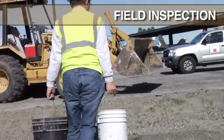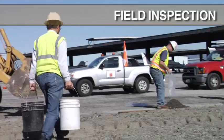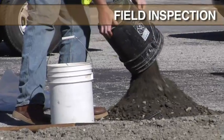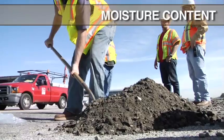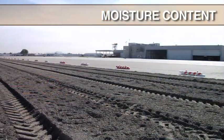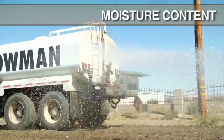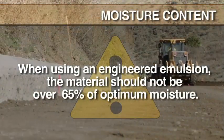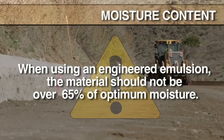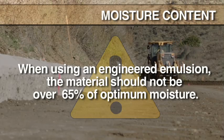Field inspection is an integral part of the FDR process. Here, a sample is taken to determine the in-place moisture content of the conditioned road. If the reclaimed material is too wet, it will need time to dry out to prevent a pumping subgrade. If it is too dry, water will need to be added. When using an engineered emulsion, the materials should not be over 65% of optimum moisture. The optimum moisture should be determined in the mix design.